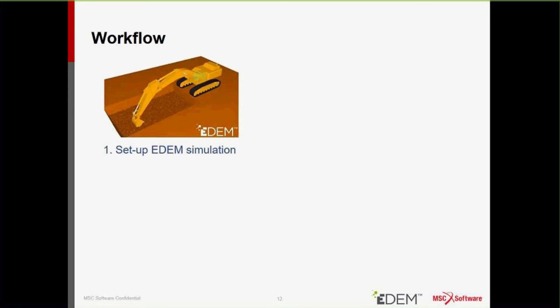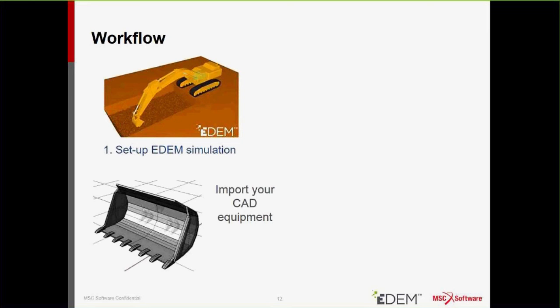So, engineers can start out by setting up their EDEM simulation. For those of you who have not used EDEM before, there are two key aspects to this. One is to import your equipment design into the software, and EDEM will allow you to import a range of standard CAD formats. Once there, you're able to define either a series of simple dynamics in the software, or obviously then subsequently link it to Adams itself.